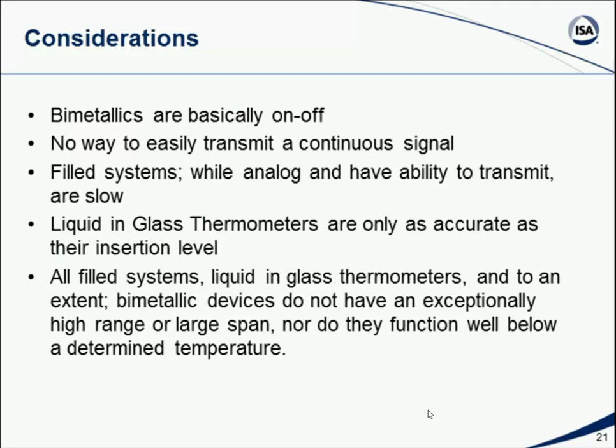And certainly all filled systems, whether it's a thermometer or one of these gas or liquid-filled C-tubes, and even to some extent bimetallic devices, most of these devices have some limits to how high and low a temperature they can operate over. In other words, if they're liquid-filled, the liquids tend to freeze. If they're mechanical in nature, if they get too cold, the mechanical aspects tend to fail and the metal gets very brittle. If the temperature gets too high, liquids boil away and metals bend and warp. So there's usually a very limited temperature range over which we can use these things. So they're not necessarily the best devices to be used.